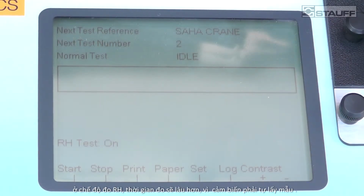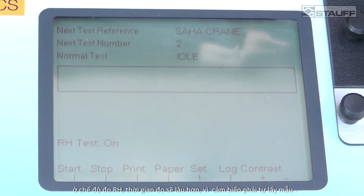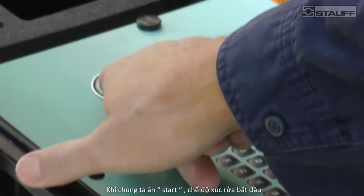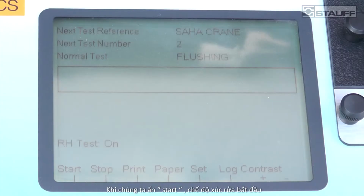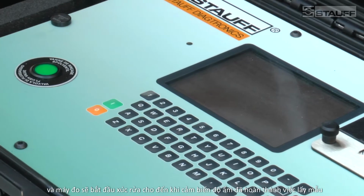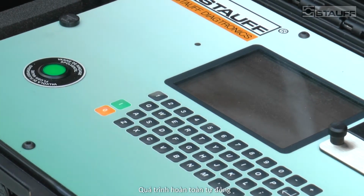When we take the moisture sensor test, it actually takes a little bit of time for the sensor to adjust itself, so it needs to calibrate itself. So it takes a couple of minutes before the actual test commences. So once we press start, the flush valve will come on and the particle counter will be flushing the fluid until the moisture sensor has been calibrated and it's ready to take the test. The whole process is automatic.